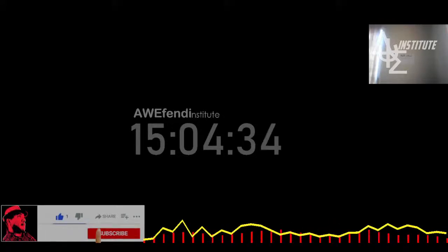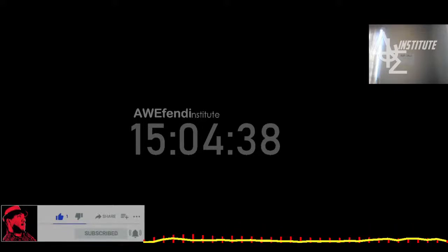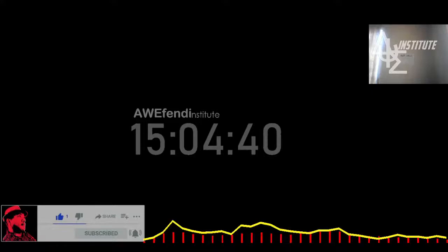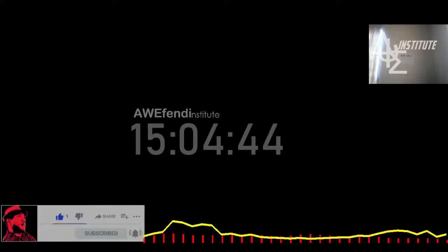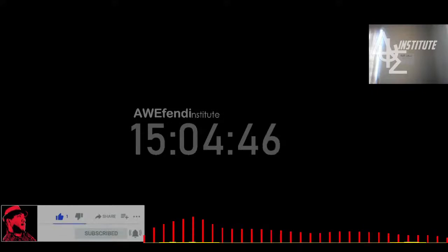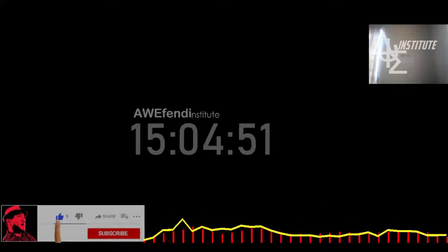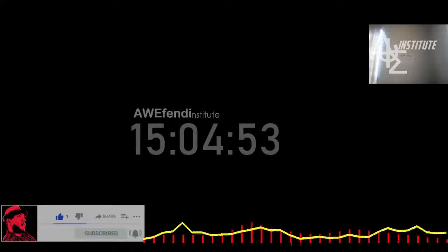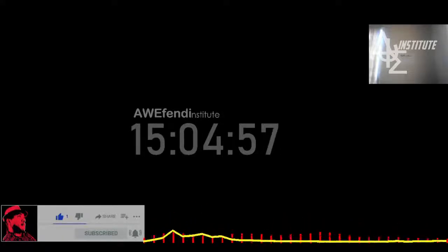And then I like to use this preview inside faces feature just to check if all the red faces are indeed contained in the geometry, meaning that it is watertight. If it, for any reason, is not watertight and you see these red faces everywhere, you can use this animation slider bar here to understand where it's flowing out, and quickly go back and fix your geometry accordingly to make it watertight.